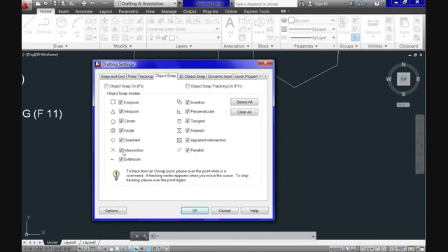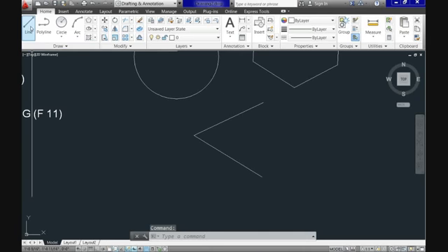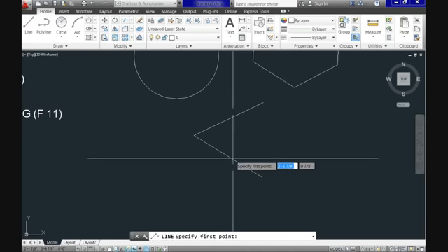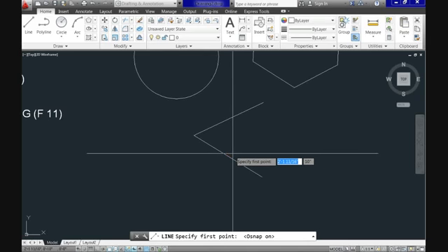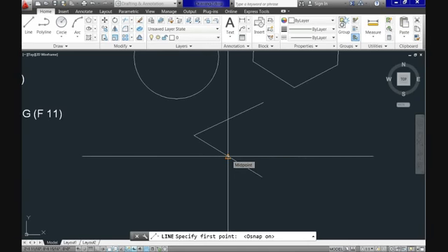To see all of the available options, we need to go here, right click and select settings. Then in the object snap tab, we have all the possible options. By checking or unchecking any of these choices, you're telling CAD whether you want to get those points as a suggestion once you get close enough to them when hovering over any object. In my case, I will only uncheck the nearest point because it's not very precise or accurate and sometimes interferes with other points. You can try checking and unchecking some of these on your own and see how it works.